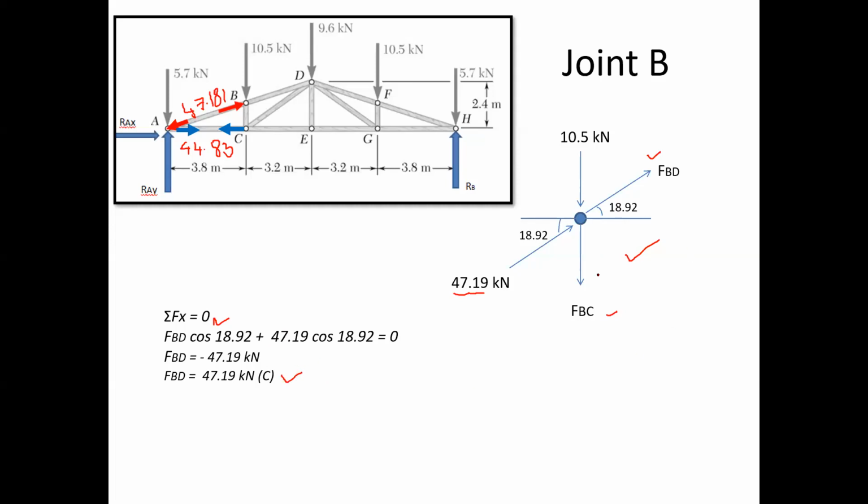Now, can you just calculate what is FBC? And you will be telling me the value of FBC. Okay, some of you are solving. Utkarsha shared some answer here, FBC. The remaining students, do summation Fy is equal to 0. Do this calculation, summation Fy is equal to 0, and get what FBC equals. And you also tell me what is the nature, whether it is tensile or compressive.